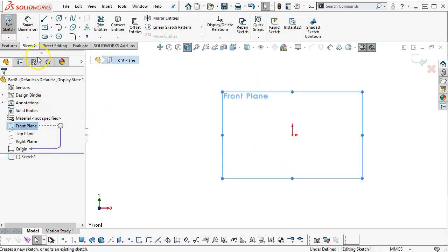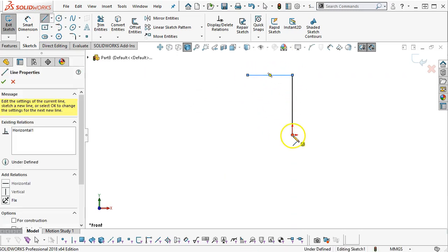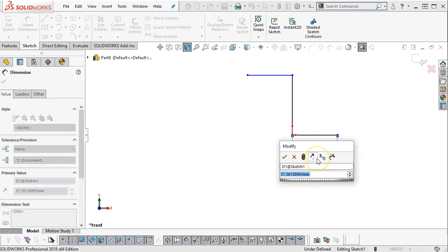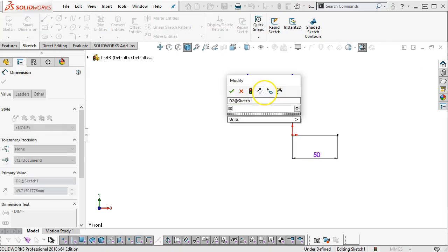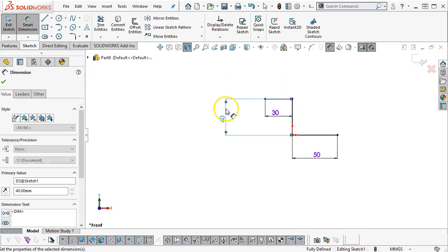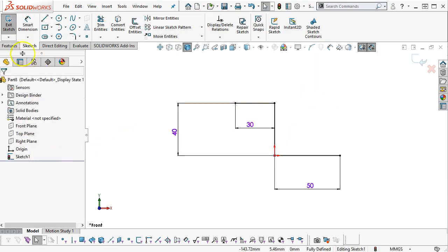All right, so front plane. Set this up. Get the legs drawn. All right, so we're 50 on the bottom, 40 on the top, except the 40 on the top does not include the 10 millimeter thickness. And then the overall height, we're 10 millimeters. Okay, 40 millimeters to the base. So since we're on that inside dimension, all right, so that gets us fully defined.